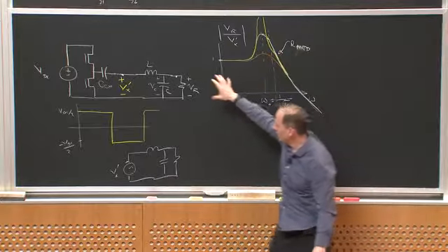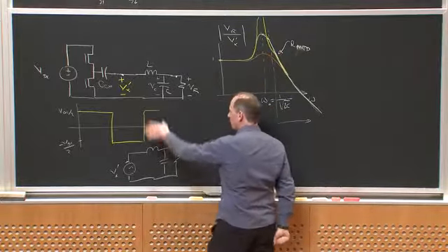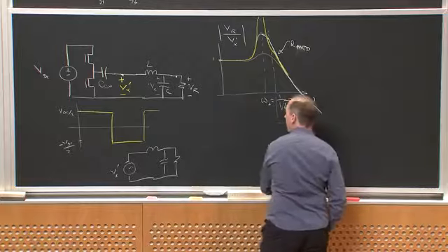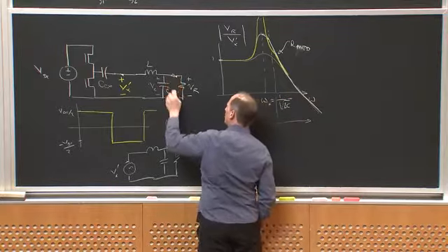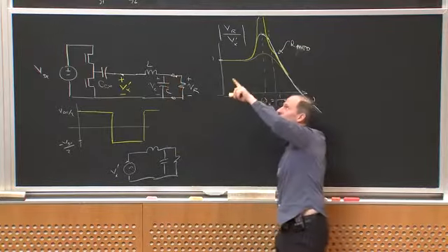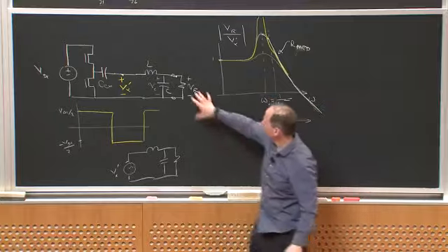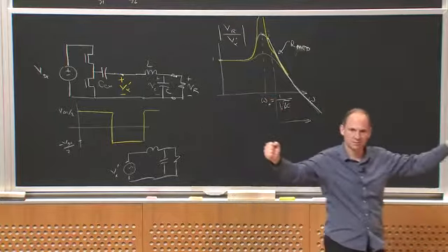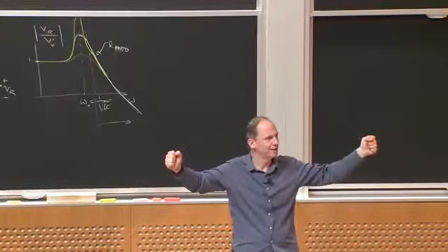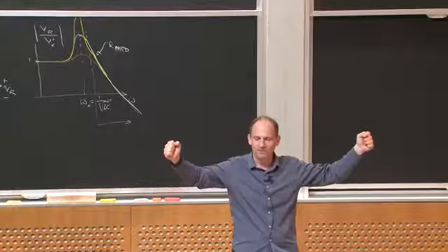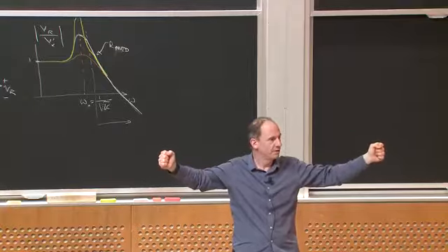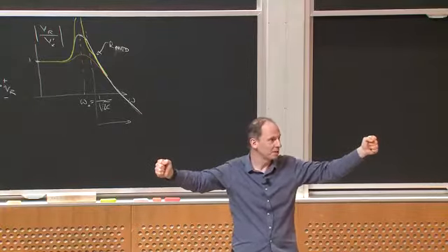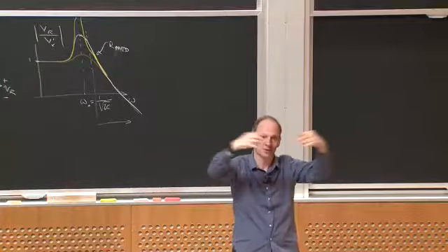So this kind of network is often what's used if you're going to have a fluorescent bulb. If you think about one of these fluorescent bulbs, what is it? It's a tube with low pressure gas in it. If the lamp is off, that has a really high impedance, because it's just two electrodes with some gas in between.